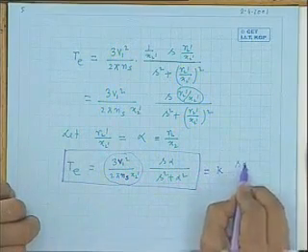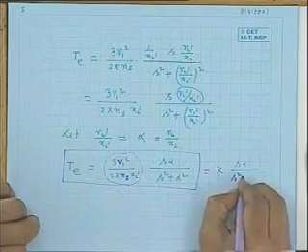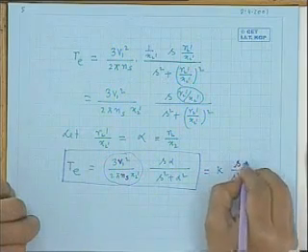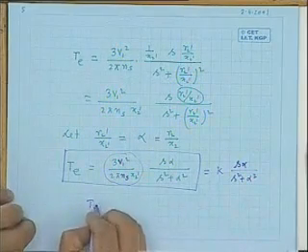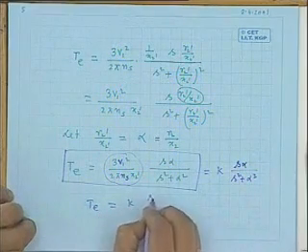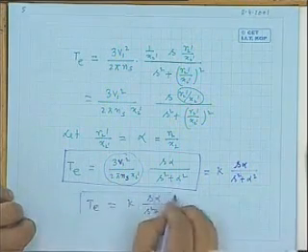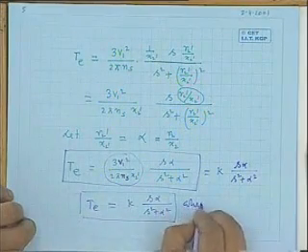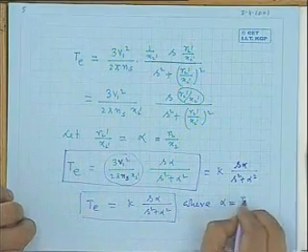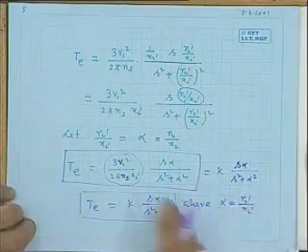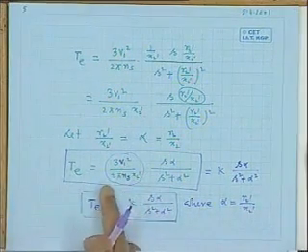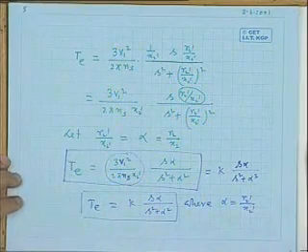So this is sometimes written as some k into S alpha by S squared plus alpha squared. When you neglect the stator impedance of the machine, the expression for the torque is of this nature, where you should remember only that alpha is R2 dashed by X2 dashed and k is 3V1 squared by 2 pi ns X2 dashed. This is the torque developed by the machine when it operates at any slip S.